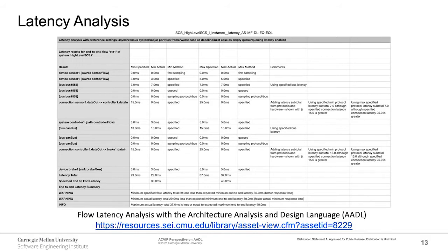It does so based on latency budgets assigned to different architectural elements, as well as design information as architectural designs evolve. The AADL model may range from a functional architecture with latency budgets at different levels of decomposition, to a task and communication architecture with execution rates mapped to a hardware platform supporting partitioning. The fidelity of the analysis is determined by the details in the AADL model.